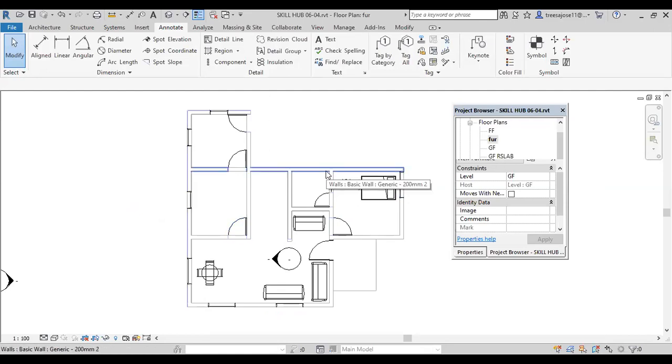okay, then visibility, where we can create the template. For example, I need to apply these particular settings, maybe in the first floor, where we also have one furniture plan. Then I have to set all the parameters there also. That time it is difficult, because in the first floor furniture plan also, you go to the doors, line weights, walls, and that is not that easy.